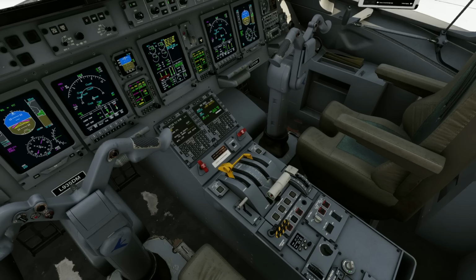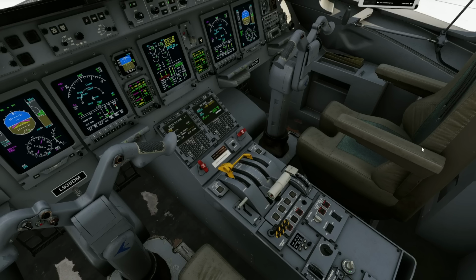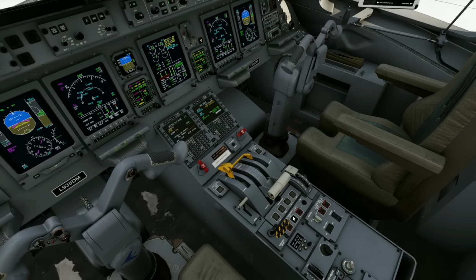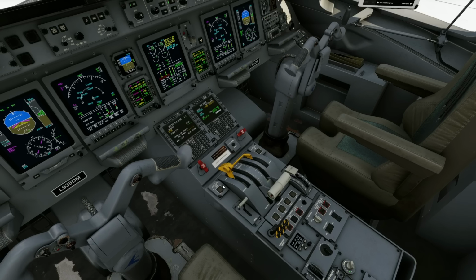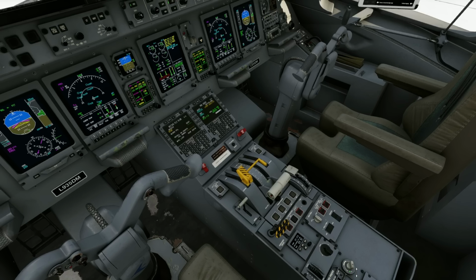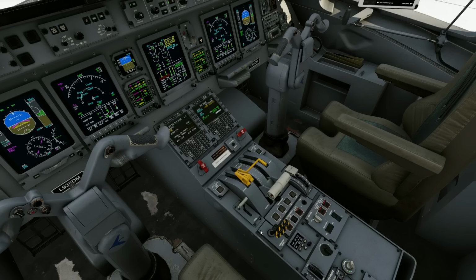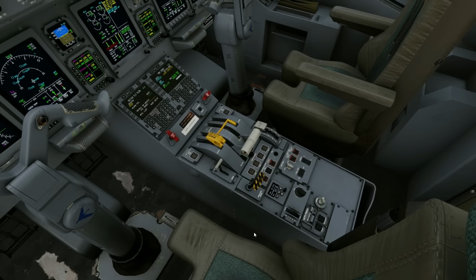And you can see that we got the alarm, and the pusher went forward to break the stall before giving me my yoke back. So that's a cool new feature. Hopefully you don't experience that firing on you. That would be bad. But it's cool to test, and it's actually one of the required pre-flight tests. So go ahead and lock that.